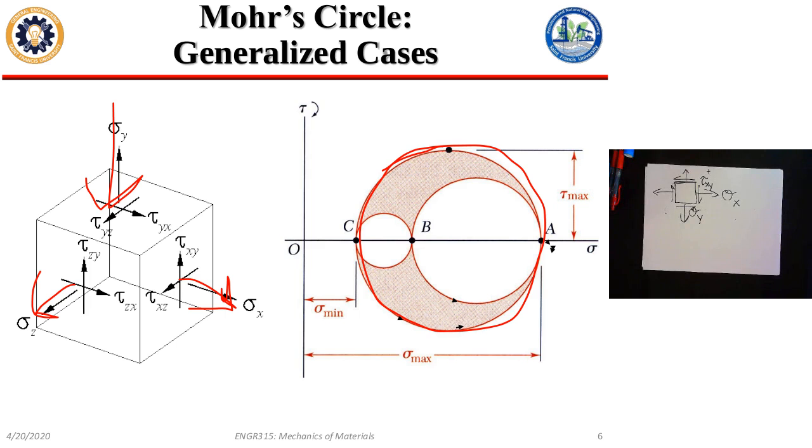So I can draw between one of these stresses and that one, or one end of my xy circle and sigma z. And then draw your last circle from the 2 points that you haven't connected yet, pretty much. That process makes sense?